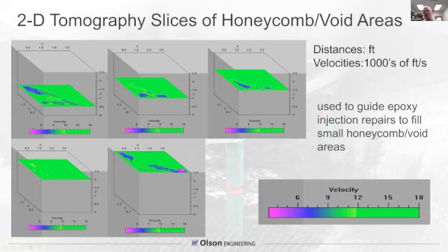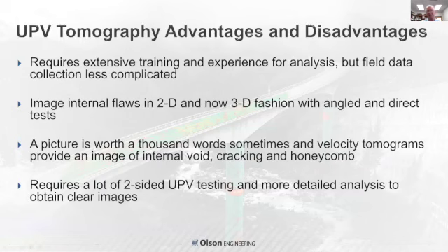I should point out that research has been done by the Portland Cement Association that showed for just a 5% loss of concrete density, so you drop from 150 pounds per cubic foot to 142.5, that corresponds to a 25 to 30% loss of compressive strength or flexural strength or tensile strength. So you really do need well consolidated concrete to achieve your strength. So not having it can be a severe penalty. If you lose 10% of density, it's a 50 to 60% loss of strength. So you definitely want well-consolidated concrete.